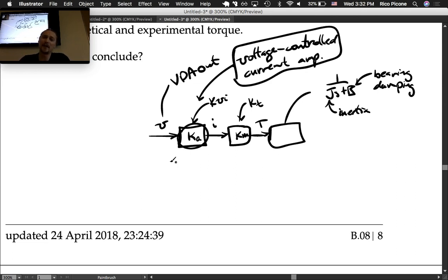Yeah, supplying power to a motor is something that a lot of applications need. A lot of times in industrial applications, you're going to see AC, big industrial applications. One of the biggest drawbacks with those is it's relatively hard to do control and closed loop. Even speed control is hard. Position control is not even worth it.